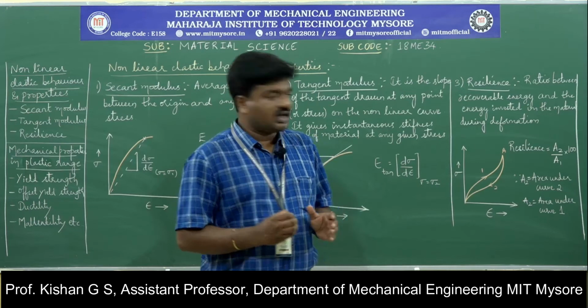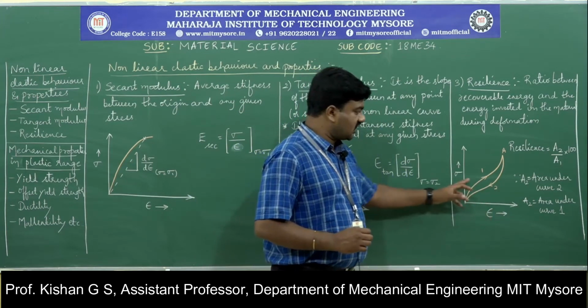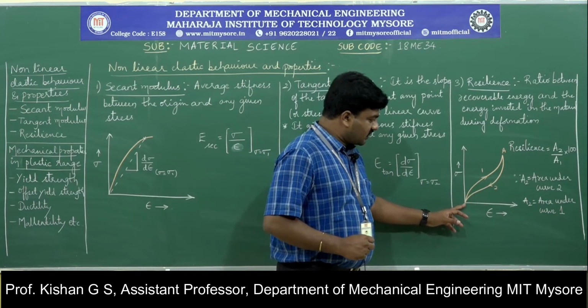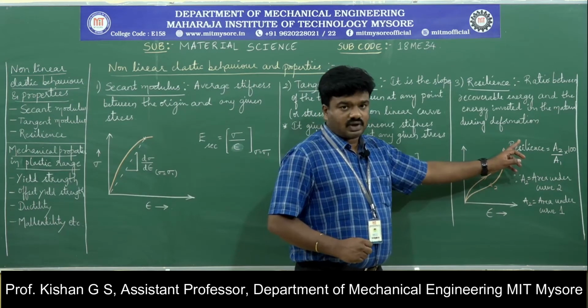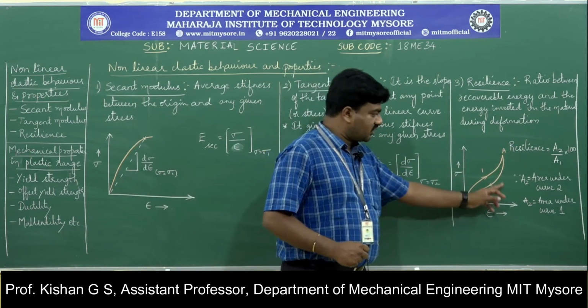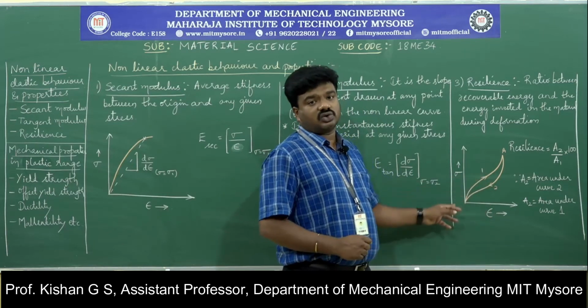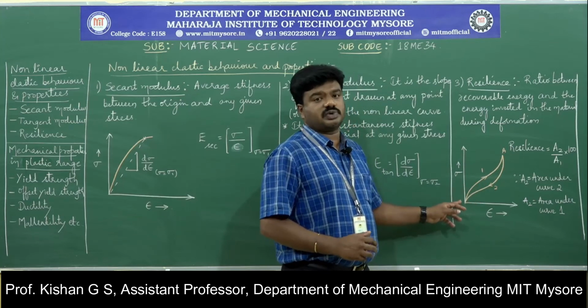being unloaded. Here in this particular stress versus strain diagram, you can just observe the curve. The curve that represents from the origin to the point A through 1 is the loading condition, and the curve which represents from A to the origin through the number 2 is considered to be the unloaded curve, or the response of a material once the load is being removed.